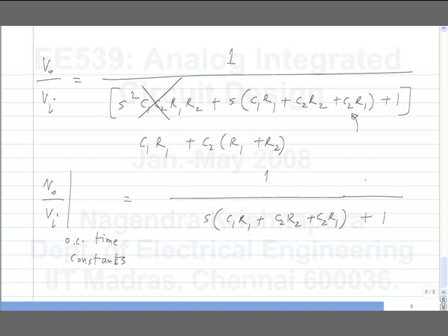The first order function cannot reproduce all the features of the second order function, but when you are calculating delays and so on, which is of interest when you do this Elmore's method, or especially when you do it for digital circuits, you are only interested in how much total delay there is. For that, it's quite useful. You guys have seen this in your digital course or what? Okay.